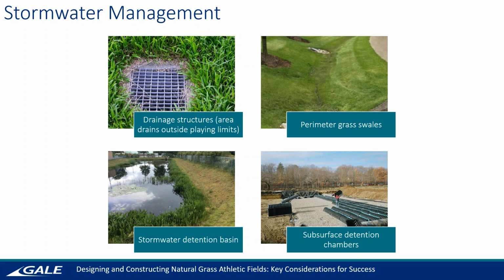These ultimately discharge, depending on where you're at and what the site dictates, into either your stormwater detention basin that you see here at the bottom left, or into some type of detention system. Right here, we're showing a subsurface detention system made up of chambers. These could be adjacent to the field. Some of them can be done under the field, or some of them can be done a little bit down gradient, and they can have paved areas on top of them. They can have parking on top of them. They're very useful to be able to maximize the available land use you have in your area.